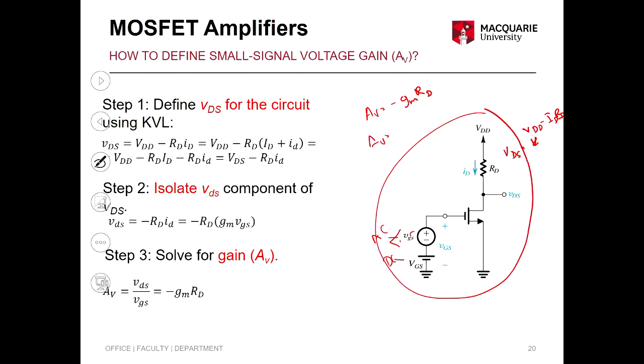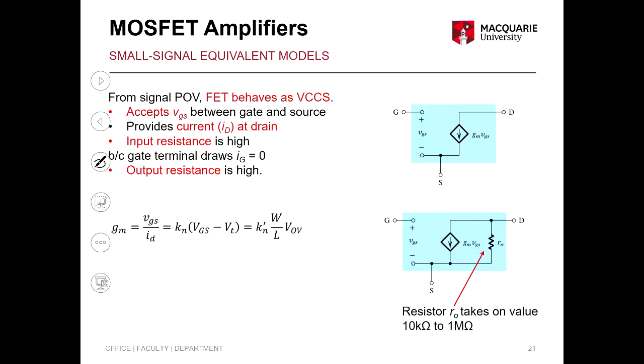But when you have 2 transistors or 3 transistors, it gets very hard to solve these equations. Say, for example, you have another transistor in parallel to that, and they both share the same output. It gets confusing, and I mean, you can still work it out. It gets more linear equations, more algebra. What is easier is to come up with the equivalent circuit model, so that you can look at it and say, okay, these are parallel, I can just simplify it, things like that. And that's why we come up with an equivalent model for the small signal circuits.